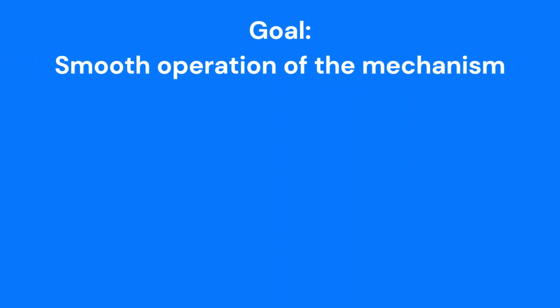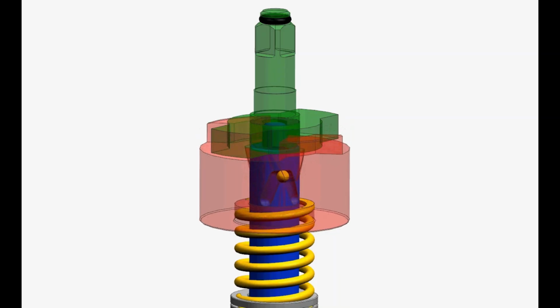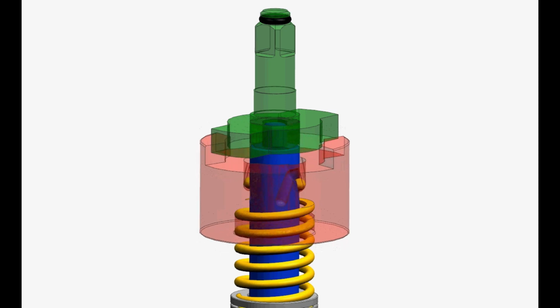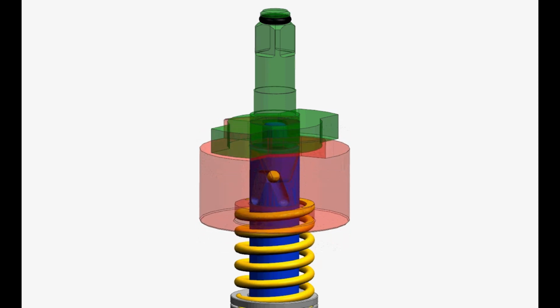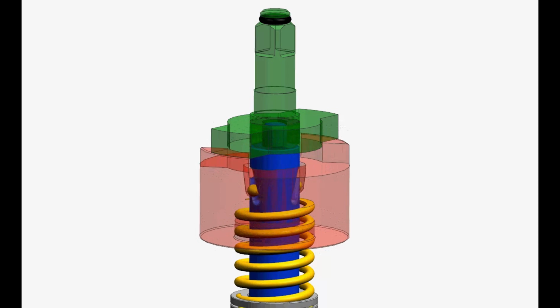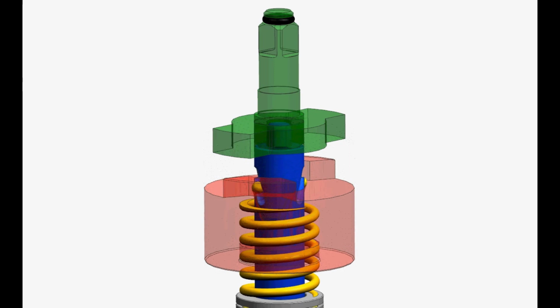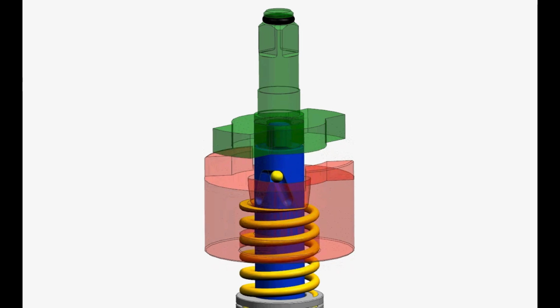The spring, the diameter of the driveshaft, and the angle of the V-grooves need to be chosen correctly to ensure smooth operation without any malfunctioning of the mechanism. In other words, if rotation of the hammer is blocked by the anvil, the motor torque must be able to overcome the spring force with the ball and the angled groove and retract the hammer from the anvil. The spring must also not be too flexible, as this will cause the hammer to retract too far, causing the balls to lock or the hammer to return too slowly for the next impact.